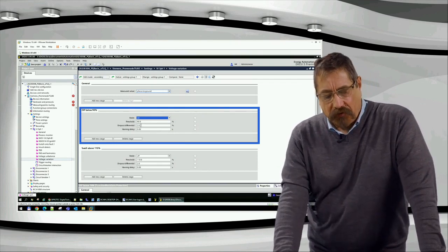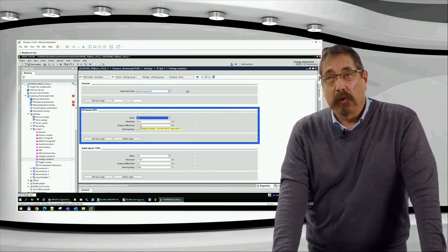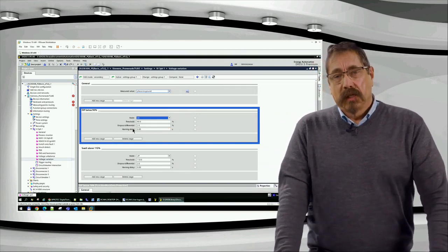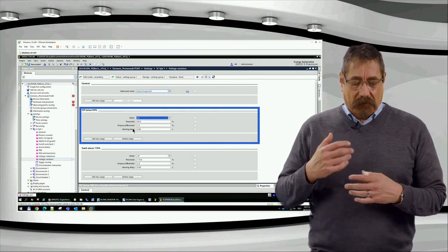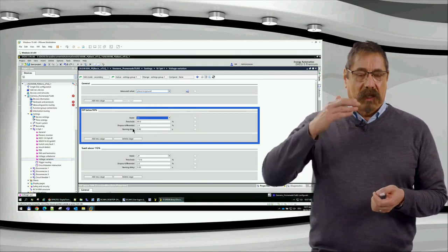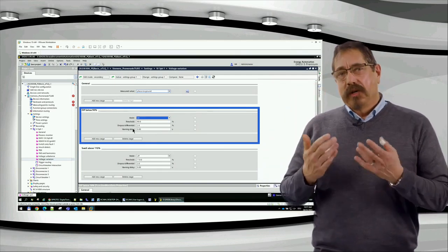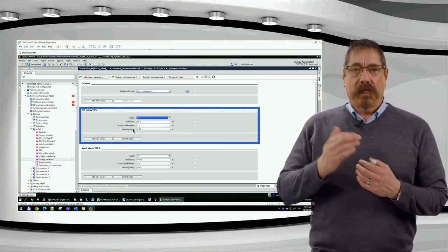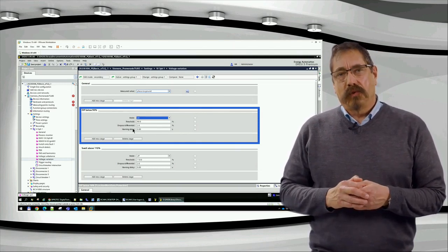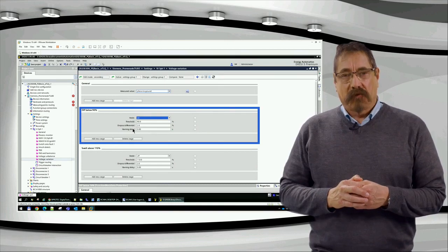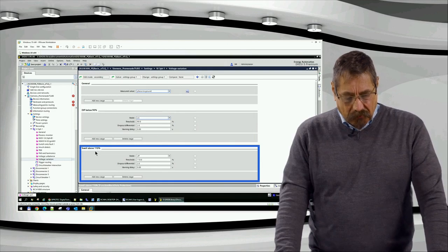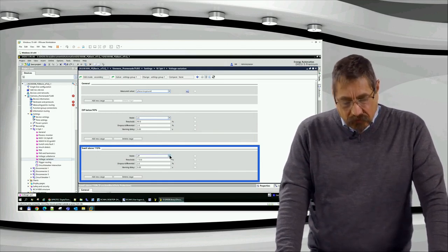Yeah, the dropout differential, what we in the power quality context very often call hysteresis, is per default 2%. When this event warning will be fired too often because the signal which is measured is, how to say, too nervous, you can increase this dropout differential to not have too many events or warnings fired. So the swell above 110, switch it on.